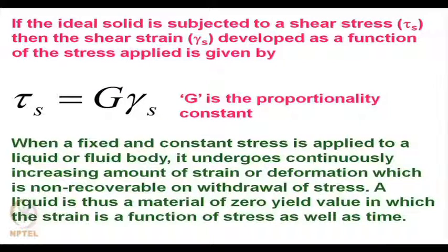If you consider a material as made of imaginary layers, the shear stress is applied on the topmost layer, that causes some deformation on the topmost layer, and the amount of deformation is less on the layer below that. This happens due to the frictional force or resistance offered by the bottom layer on the topmost layer.